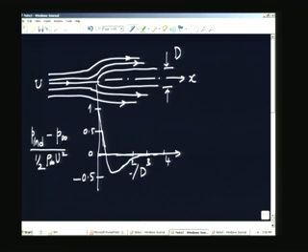And what I have done is I have plotted a simple sketch here. This is just to understand the proportioning of the Pitot static tube. So, I have again indicated the Pitot static tube as a bluff body, and I am looking at the change in the flow around this body. The flow is coming with a velocity u, and because of the body it has to go around it. We are assuming that the flow is ideal flow without friction. The friction effect can be taken care of by a suitable factor a little later on, we will come to that. The diameter of the probe is d.